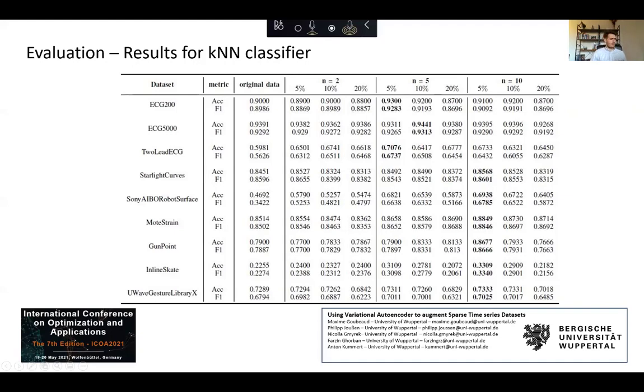examine better results. And the performance was significantly better, and we therefore recommend using white noise windows for the KNN with a window size of 5% and n/10. That shows the best results, as you can see here, in 6 out of 9 cases. And n/2 for ECG signals can be a good choice since it gives the best results for all 3 ECG data sets. You can see it here.